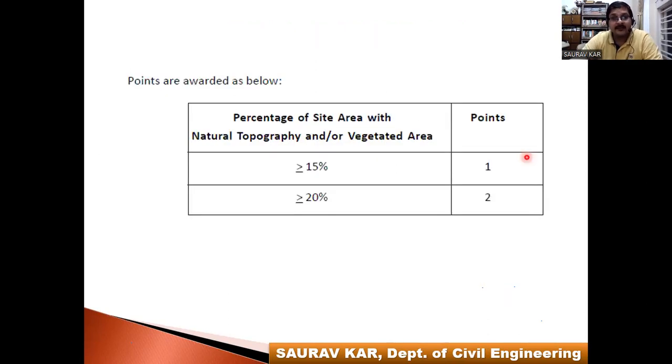See here, points are there. If the percentage of site area with natural topography or vegetation will be more than or equal to 15% of the plot area, that is site area, 1 point. If it is more than 20%, then 2 points. So for example, you have a plot area of about 1000 square meter.